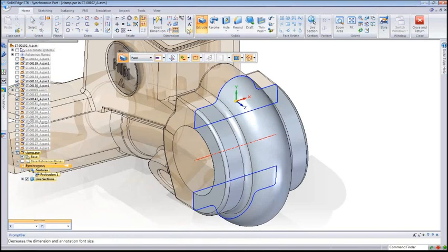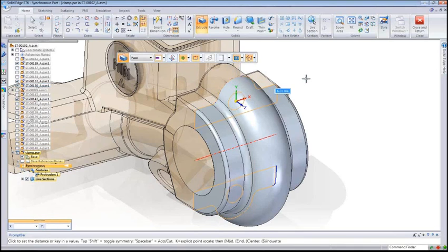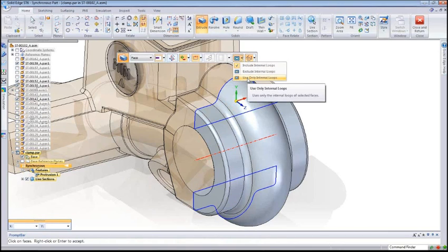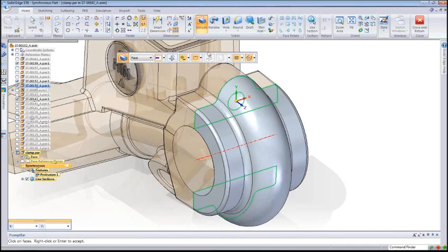With that said, I'm going to choose extrude. And I could choose the whole face. You know what? I'll do it this time. Normally I don't do it this way, but I'm going to say only include internal loops. Oh, that's interesting. So I'm going to click on the same face, and I'm going to click on this face. And I'm going to right-hand click, and it's only, whoops, wrong one. I did it wrong. Extrude, and only internal loops. Let's see if we can get this right. Here and here. Right-hand click.